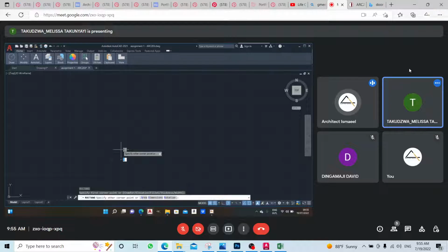Yes. Is it dimension? Is it a D? So it's time to use it. So I'm able to use the D command. What does D mean? D means to put a dimension. For example, I do have a specific dimension for this rectangle.